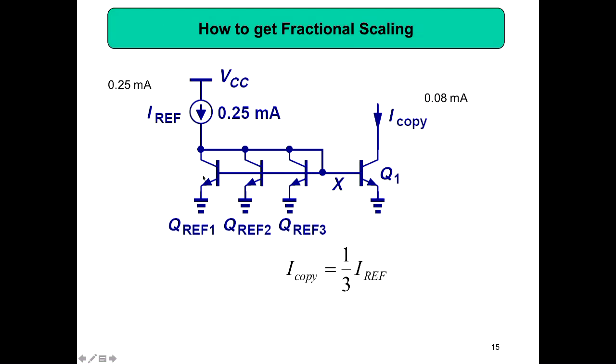So when you connect 3, 0.25 milliamps is coming here, then divided by 3, 0.08 milliamps will go through this collector, 0.08 through this collector, 0.08 through this collector, and then your Vb corresponds to 0.08 milliamps. That is the Vb that you are getting. 0.08 milliamps will decide what the Vb value is. Then here you get 0.08 milliamps.